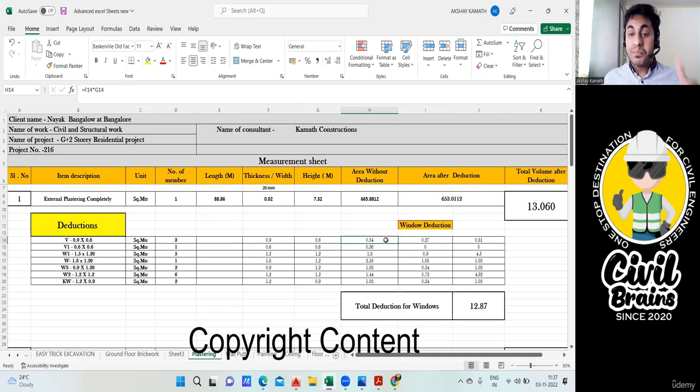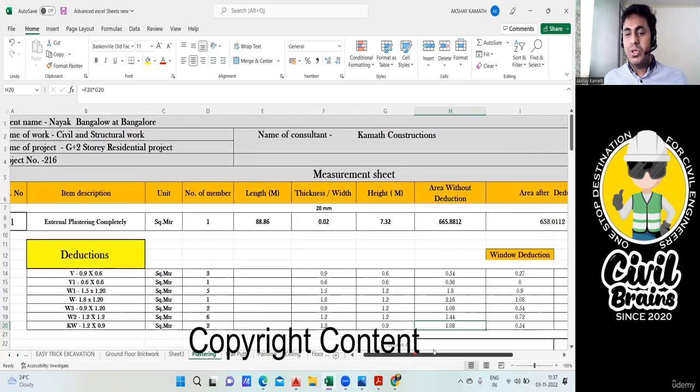Now what you do here is very important. Here you just multiply 0.9. Here you have to multiply the area of window, single window. For example, see, I multiplied 0.9 into 0.6. That is area without deduction. Here you write again, 0.6 into 0.6 is 0.36. Now 1.5 into 1.2 is 1.8. So in this way, you just multiply all these things. 1.2 into 0.9 will give me 1.08. Okay, up to here you are done.